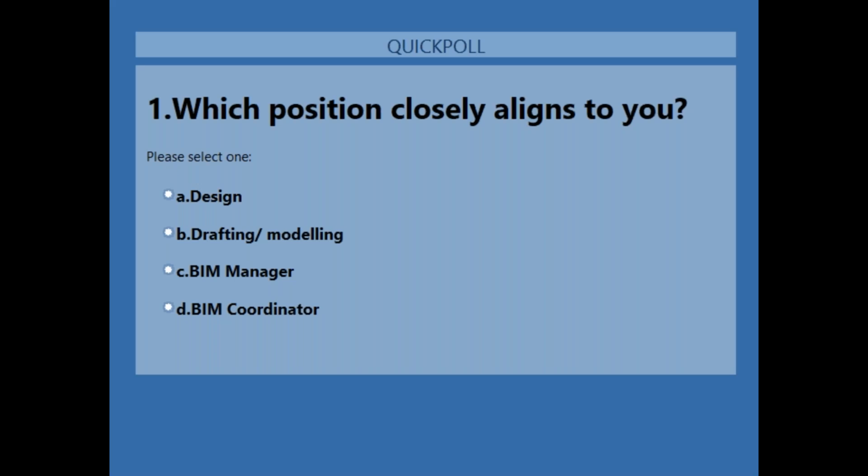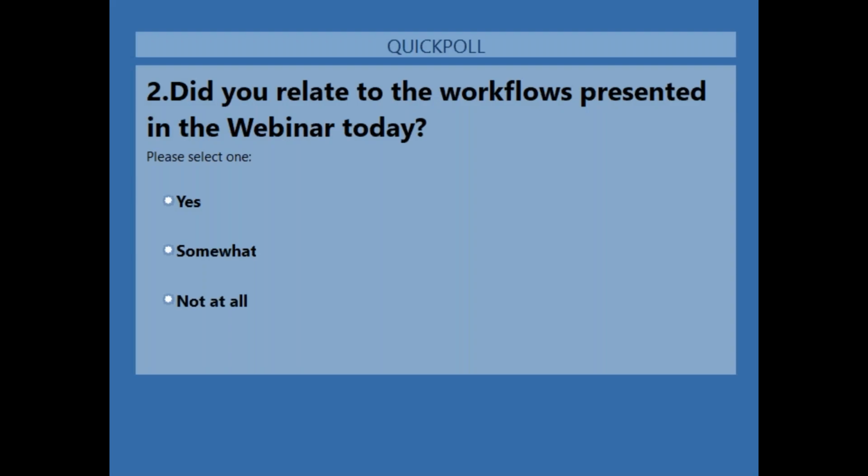It's very handy to cross-check whether both projects you're referencing have a similar base point or survey point, or whether they are really far apart. It also helps you acquire coordinates from a linked file and make sure the one you are working in is exactly the one you are referring to. If you want to understand more, we can do a separate call or session with you and take these points in detail, how base and survey points work in Revit.